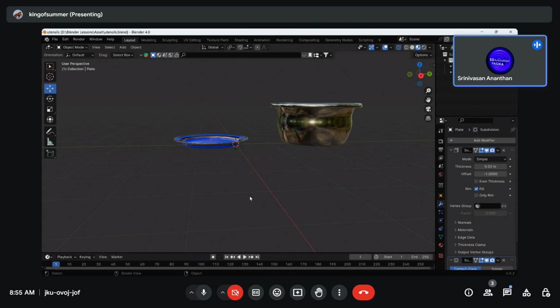You see, just one small thing I will tell you. Do you see the solidify properties on the right side? Vertex group is there. If you give a vertex group, it will solidify only for that vertex group. I will tell you maybe in the next version. These vertex groups are very powerful in shape animation. Suppose a pot is becoming some other vessel, a morphing, for that we can use vertex groups. So it'll be nice. It will be useful in modeling, in texturing, in material and sculpting.